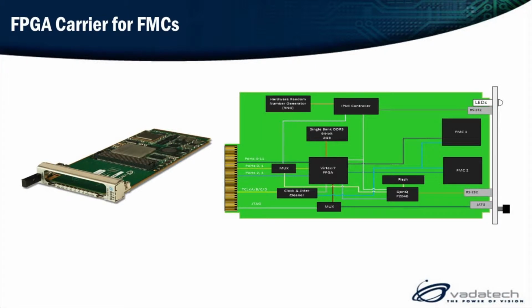So if we're combining the two, between the first case and the second case, we had inherent FPGA in one. Here, we're combining the two pieces for an FPGA carrier where you put the FMC on top of the FPGA carrier itself. In this case, I'm showing a dual FMC carrier, but in the photo, I'm showing a single, so the photos aren't exactly matching up. I'm trying to show some different scenarios here.